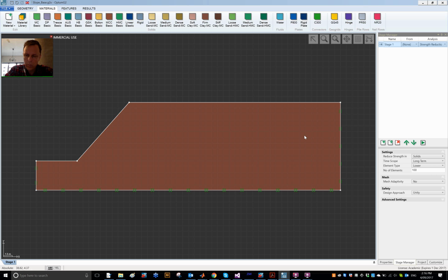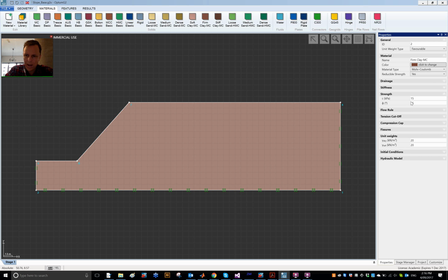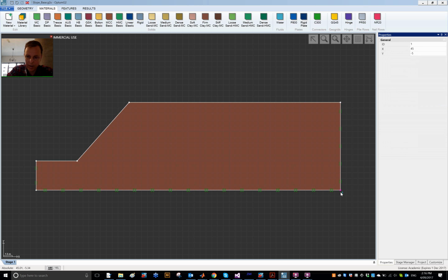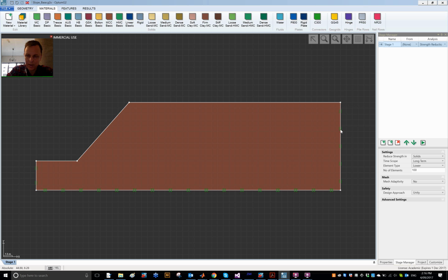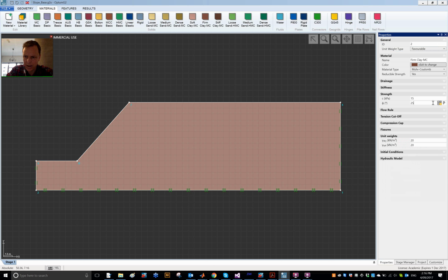So we have this, it's a little bit backward, but we need to use actually a profile. A profile defined by 2 points, say the top and bottom here, so -5 and 10, and then with the corresponding value being the same at top and bottom, meaning that we will have a profile with a constant value of the parameter in question, for example the friction angle.